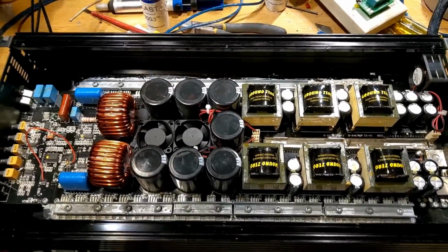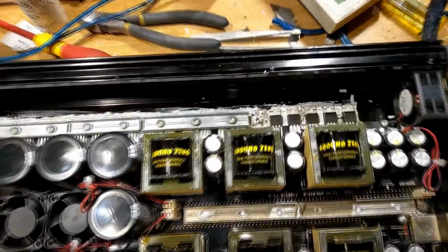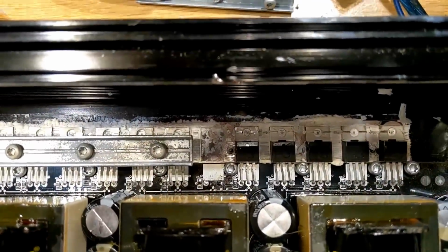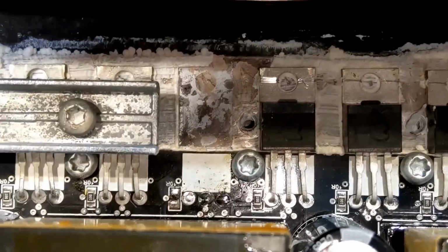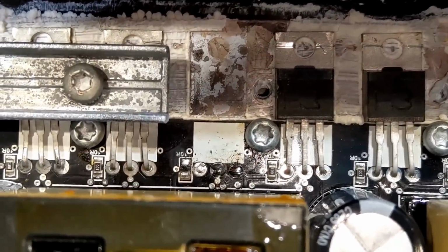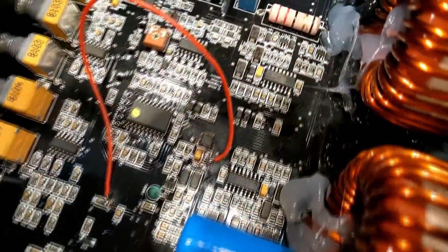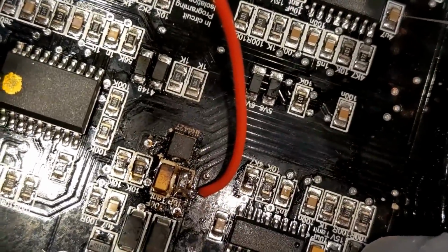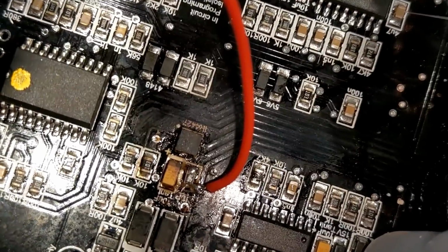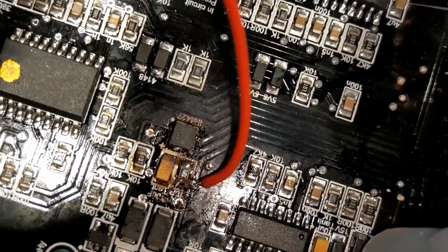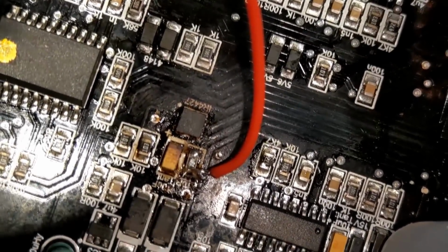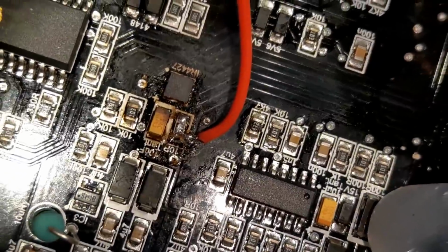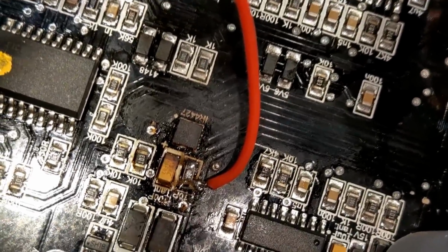So on this ground zero, or sound digital as the circuit originally was, had one FET that exploded its leg in the power supply section. Let's remove that. It sent a huge spike down the gate path. The 10R was dead. And that sent the spike all the way down here, and it completely killed the drive IC for the power supply FETs. It's not a 4427, that is incorrect marking, it's something completely different. And then when that died, it also completely killed this 10R resistor that is feeding it with VCC.